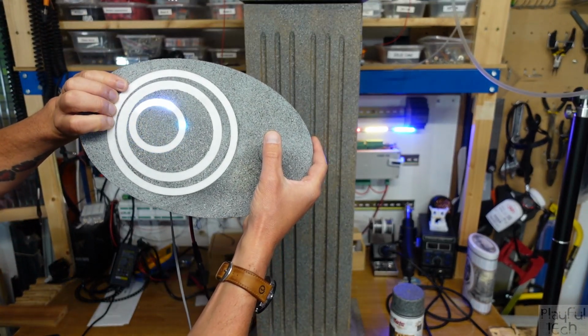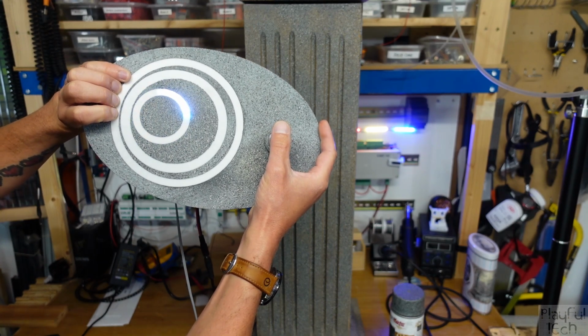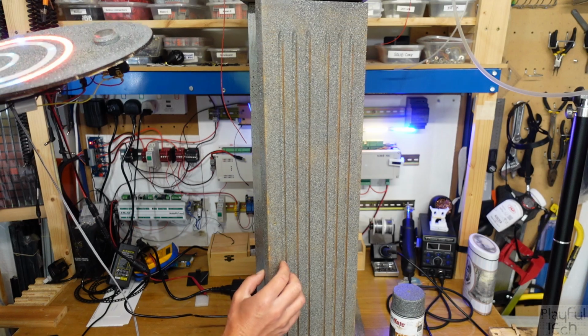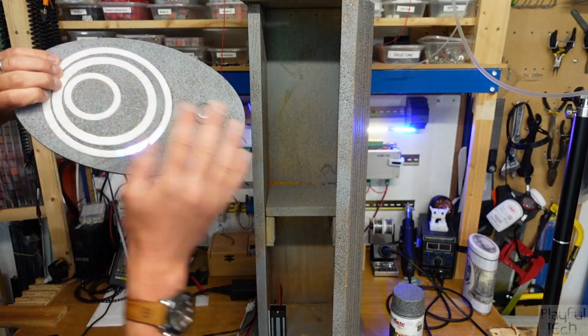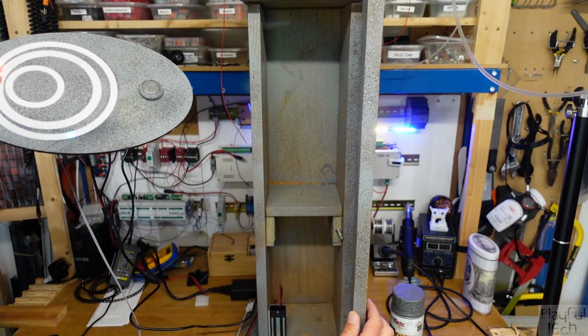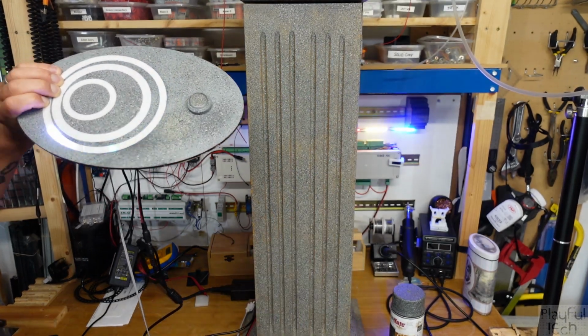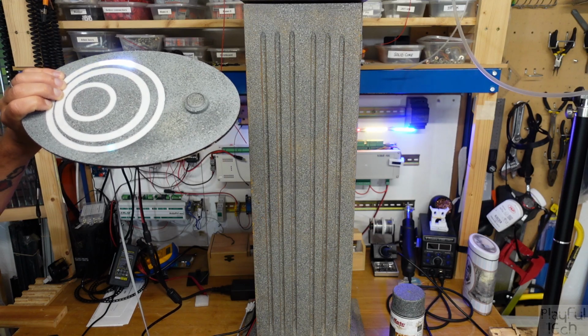So if I now just solve the puzzle, if I can actually get it correct, there we go. That triggers the relay, which releases power to this maglock here, and that is what is securing the plinth door. And then when the puzzle resets, this gets re-energized again, so you can simply reset the puzzle by closing the door again, and that is reset, ready for the next playthrough.